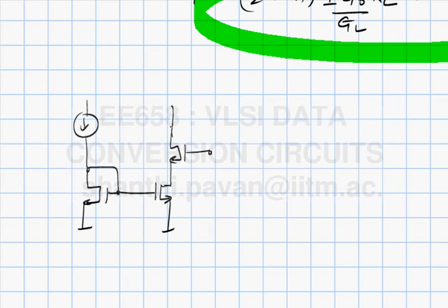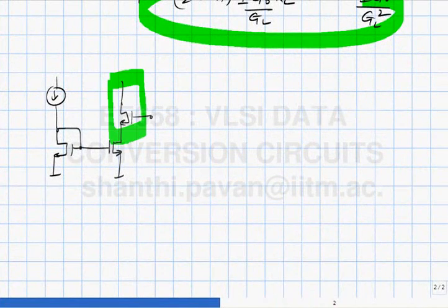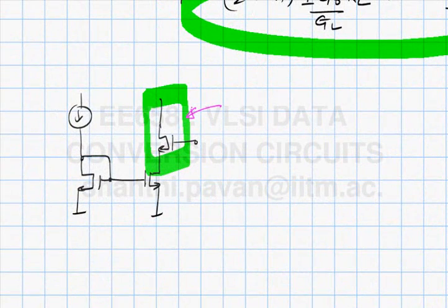In practice, the simplest current controlled current source that you know is simply a common gate amplifier. The common gate amplifier will take whatever impedance you have looking in here, and the equivalent impedance looking in here is basically this impedance at the source multiplied by approximately GMRO. This is the current controlled current source. So this will enhance the output impedance of the basic current source by a factor GMRO. And a simple way of deriving these bias voltages is the following.